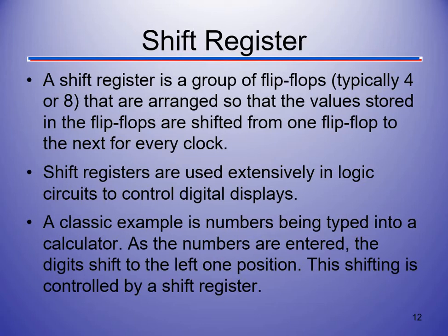Well, we use them in controlled digital displays. So if we want a whole bunch of 7-segment displays to turn on, we're going to use a shift register. On our FPGA boards, if we want to turn on all 4 or all 8 7-segment displays at once and shift logic data through them, that's what we're going to have to do: use a shift register.